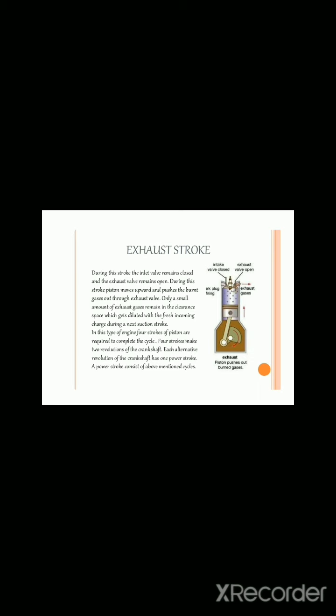Exhaust stroke. During this stroke, the inlet valve remains closed and the exhaust valve remains open. The piston moves upward and pushes the burnt gases out through the exhaust valve. Only a small amount of exhaust gases remains in the clearance space, which gets diluted with the fresh incoming charge during the next suction stroke.